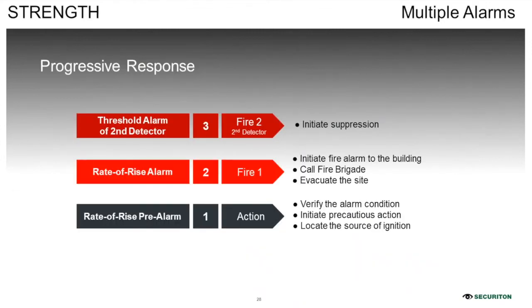With that, we also need to mention that we have a few signals available, which are the rate of rise, maximum alarm, and if it's a 2 detection system, we can also do a faster and slower detection, so that we can do a double knock solution as well. Because we have a 2-zone system, ADW 535-2, which is able to get 2 signals, you can have a double confirmation, which makes sure that extinguishing is done in a proper double confirmation. So that's also possible from our ADW.